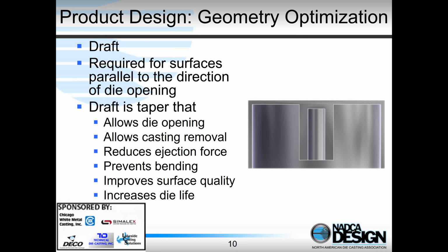So when we have draft, we have the ejector pins. They push it forward just a little, and then after just a little bit of motion, all the cast surfaces have moved away from the die face, and then ejection can occur with no further resistance from the die. So in the ultimate case, if the casting doesn't eject easily, we'll certainly push the ejector pins through the casting. I've certainly seen that happen. The casting is still very hot, it's weak, so it's really easy to do if the casting is sticking in the die. So we need adequate draft for all operations to go easily.